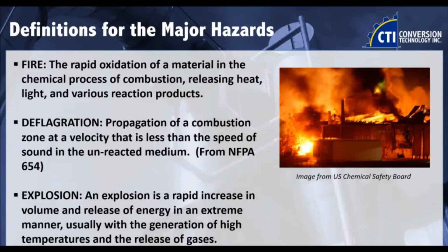I think you'd be surprised how many of the incidences that have occurred, that some of you might have heard about, were due to poor housekeeping, or what I call dust accumulation. So if rooms or pieces of equipment have the potential for dust concentrations to reach that MEC, minimum explosive concentration, then a deflagration hazard can exist.